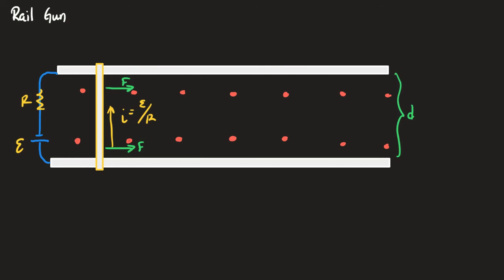But the truth is, it's a distributed force that acts everywhere along the bar. Now if you understand why I said that, you know why that's important. And I'm afraid some of you aren't really thinking like an engineer needs to, which is we need that rail to be accelerated uniformly across the rails, so that it doesn't come off the rail, right? If it was not accelerated uniformly, then it might have a path that's more like in this direction. Or worse, it might twist and get kinked up inside the rails.